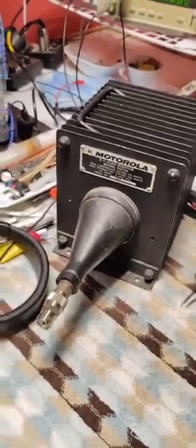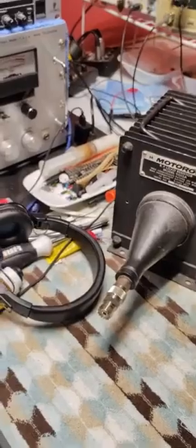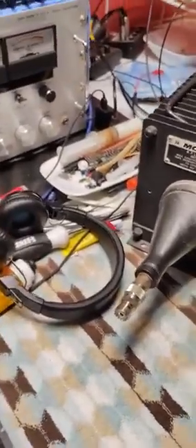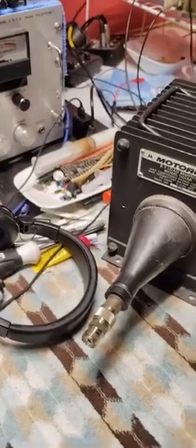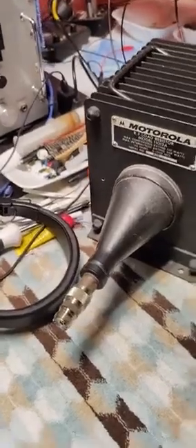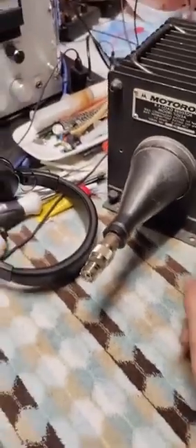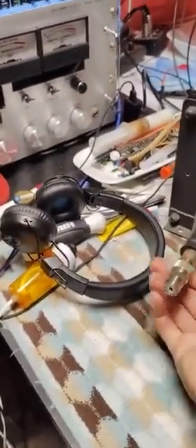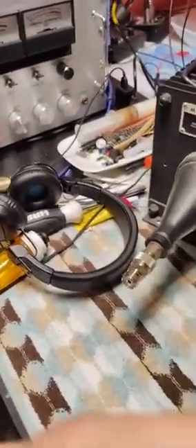because you can have a resonant antenna in the multi-thousands of ohms, and if you plug a 50 ohm cable into it, I mean, sorry, but you're going to have skyrocket high SWR, regardless of whether or not that antenna was resonant. Anyway, I think I already said that in the video that's about to be loaded up here, but there you go, I said it again.